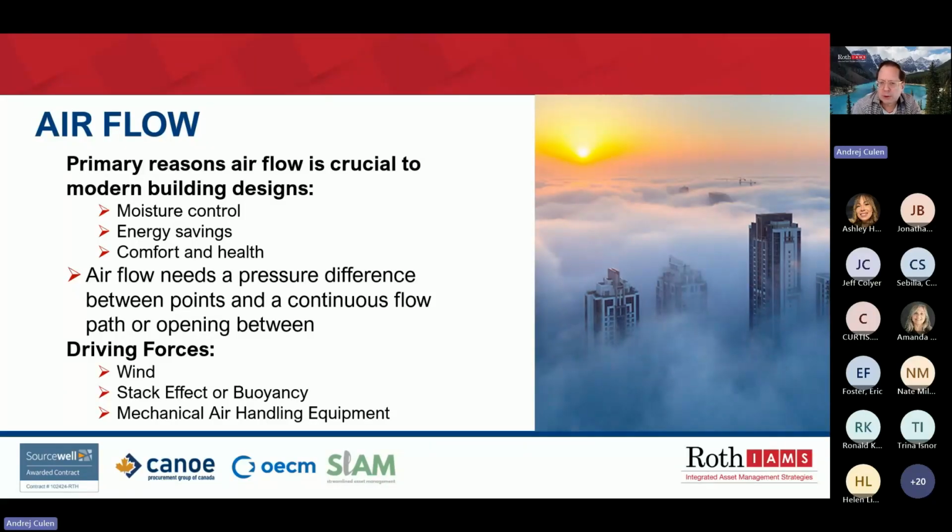Airflow through the enclosure can also carry exhaust gases, odors, and sounds through enclosures, as well as mold spores and off-gassing generated within the enclosure. Uncontrolled air leakage through the enclosure is therefore often a major cause of performance problems: comfort, health, energy, and durability.